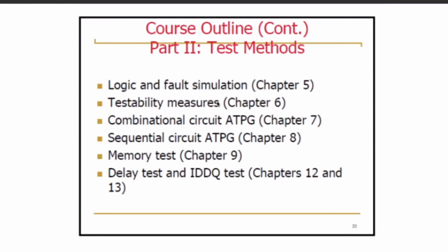We can do the design synthesis process, gate level design synthesis, and basically the DFT process on the Synopsys Design Vision tool. Here there are certain steps or iterations. You can define your DFT architecture, and you can simultaneously do the DFT on the design, and then you can evaluate the response of test generation.